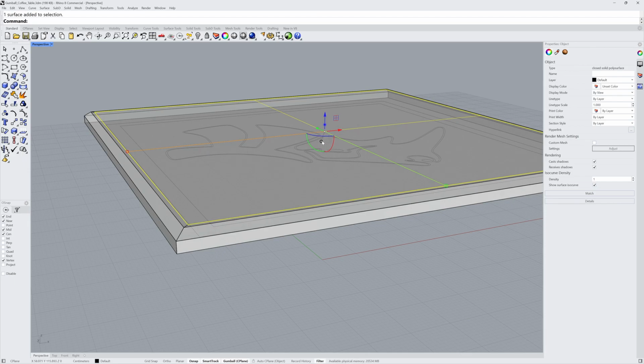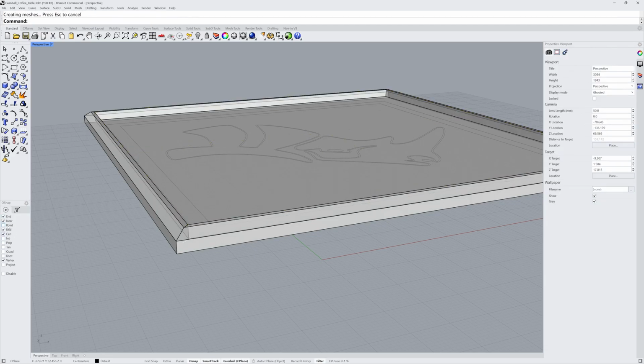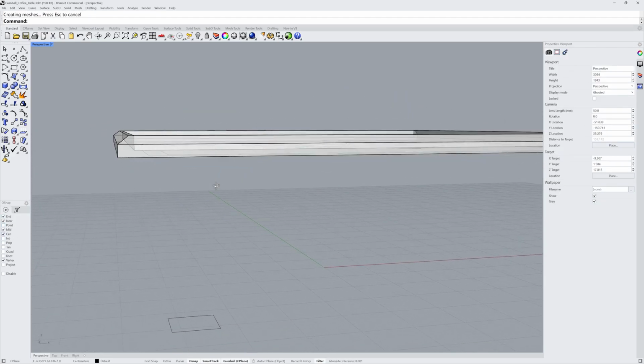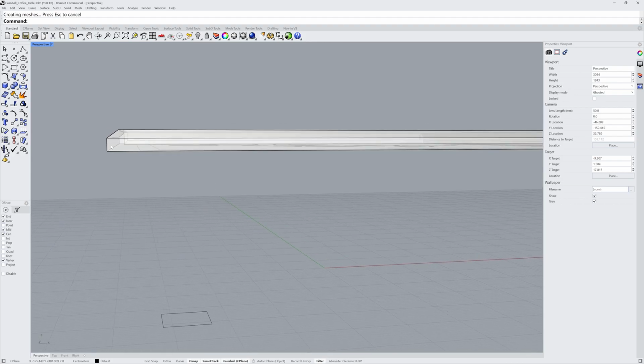By clicking the settings circle for the Gumball, I can choose the snappy dragging option. Snappy dragging will utilize your object snaps in the file, so when we click and drag the extrude handle, we can mouse over and pick up a mid-snap on that edge. Mid-snaps were enabled in my Osnap panel on the side.